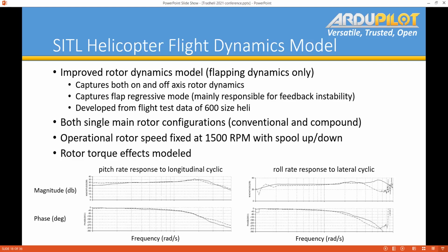But again, if you're going to use the SysID mode, because you have some of those feedback loops, you're going to have to decouple the responses in order to develop a raw model for the aircraft, basically a bare airframe model, which is what I had to do for this, right? I needed a bare airframe model.